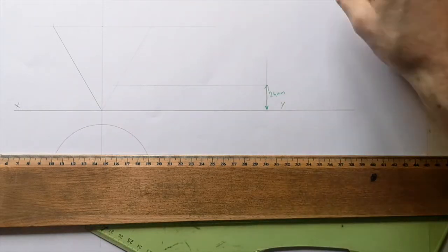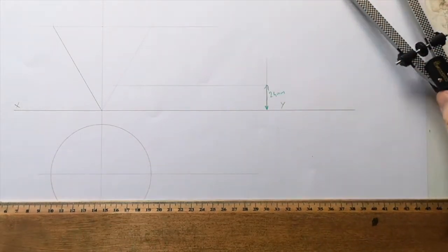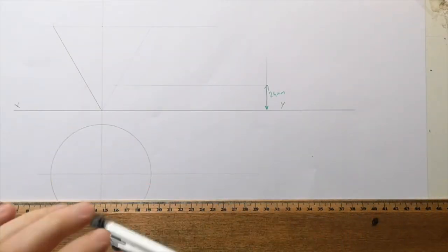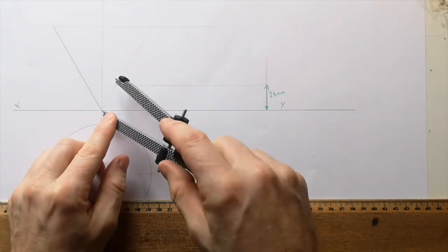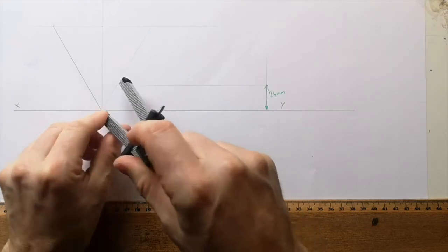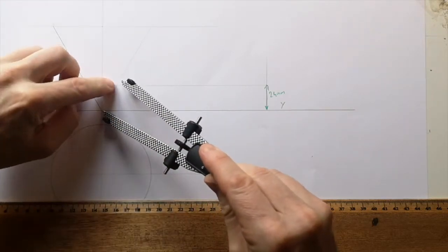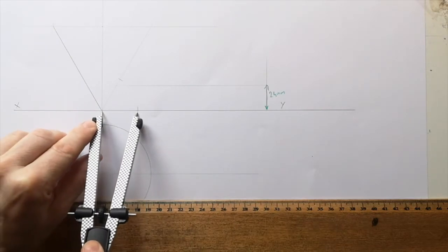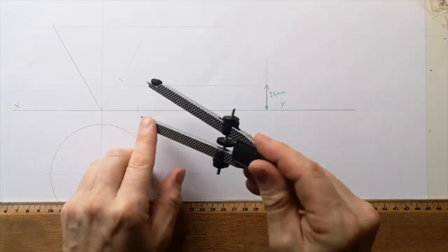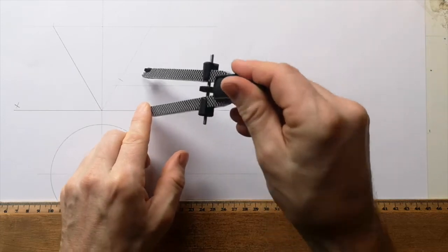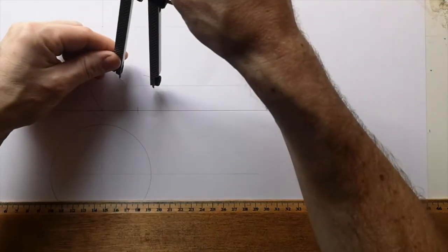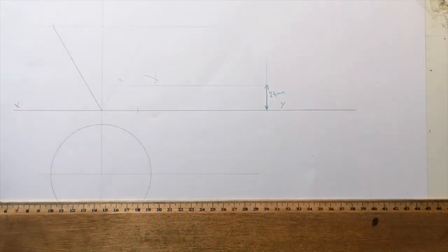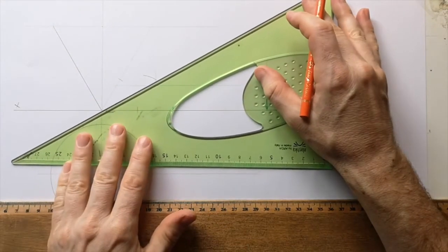Now, how are we doing the other bit? I think for a bit of variety, we're going to bisect this one, just again to see. This is one of our two techniques we can use. So there we are. Now I'm just going to make sure I don't line up with this line and cause any confusion. So my compass is just set to any distance really. Choose a fairly sensible one is better. And then there we go. There we are. And this is my bisector.